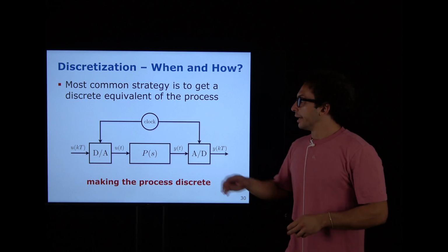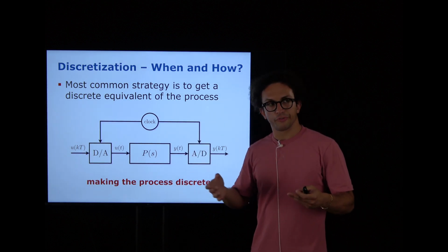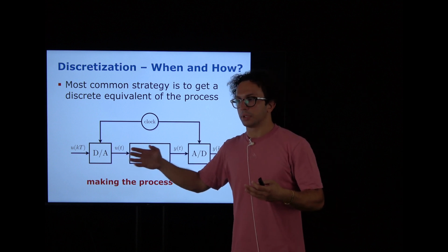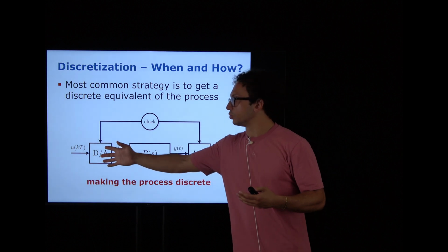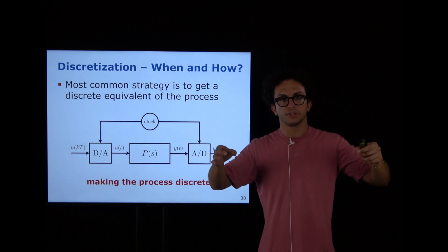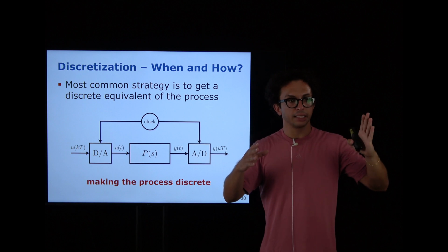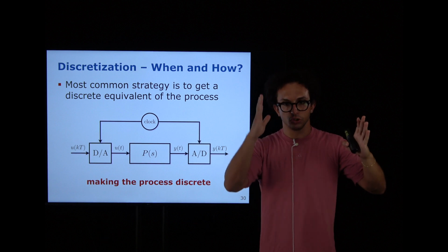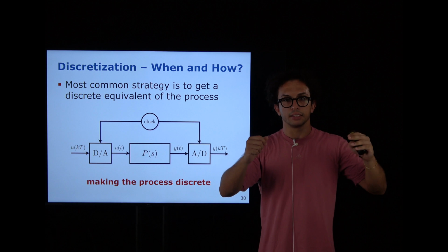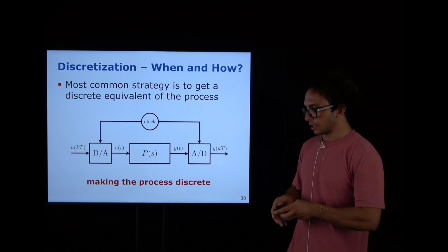So it actually gives back directly a discretized version of the output. And this clock here is just some sort of alignment, some time synchronization between this sampling and this sampling. So you want the sampling to happen at the same time so that you know that you are applying something at a certain time, and you know that at that time you also see directly how the system is changing. And so you have these two things which are somehow coordinated, so to say.